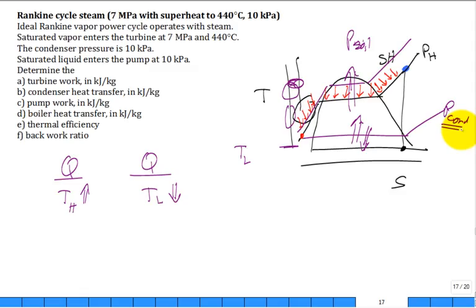Well, let's only run our power plants in Alaska. Well, that'd be great, but we have to transmit it to South Texas because that's where we need it in the summer. So basically, no, that's not going to work. The power plant would be more efficient in Alaska because it's colder. Actually, if you work for CPS, they could see the small changes in the performance of their power plants from winter to summer. Why? Lake water temperature's colder in the winter, and they're dumping heat to that lake water.